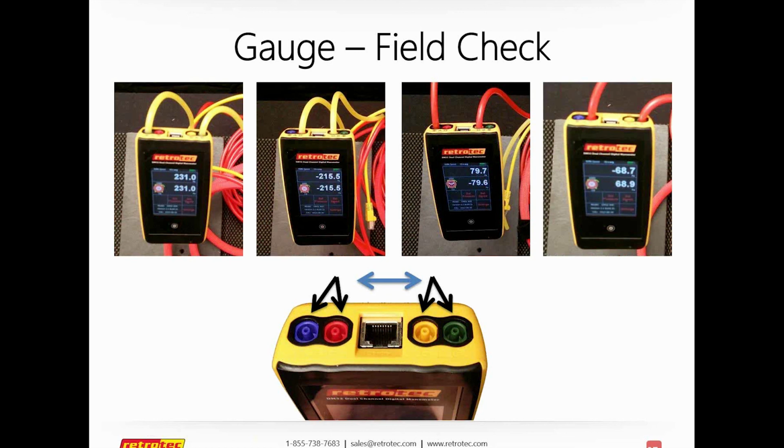So let's talk really quickly about some of those ResNet codes. Many people have mentioned to me, "Well, ResNet says that I have to get my stuff calibrated every 2 years." Well, technically what the ResNet code says is that it has to be proven to be in calibration. So it doesn't have to be calibrated per se, and this is a way to prove that it's in calibration.